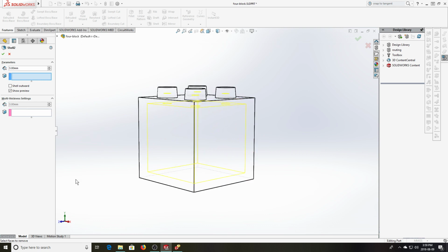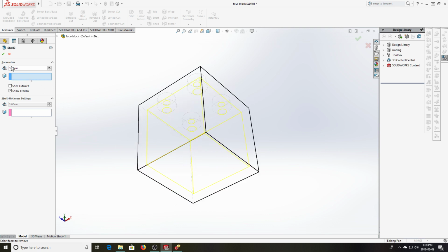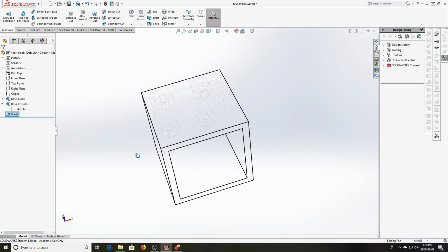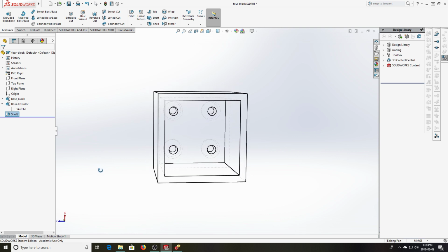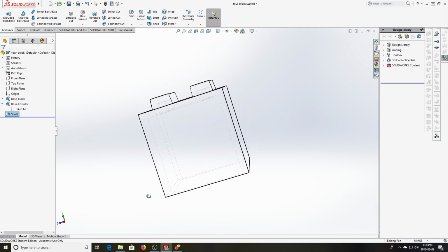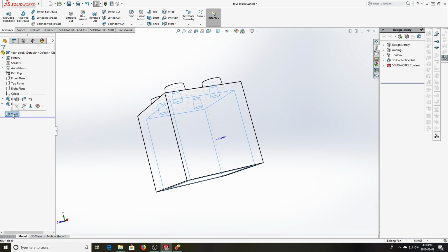So I'm going to have to look at how would I make that more realistic. Well, there's this remaining blue box, which is faces to remove. So these would be faces on the 3D CAD model that aren't going to be made into a shell. So if I pick the bottom one, for instance, then what I've ended up with is actually a hollow shell. One of the odd things about this, however, is that these little nubs, because they're bigger than 3 millimeters, have shown up as having a hollow shell too. That might not be too realistic, so I can go back to the shell command.